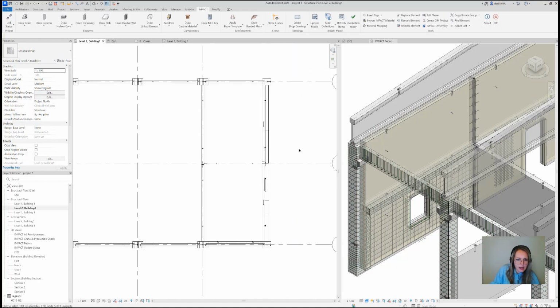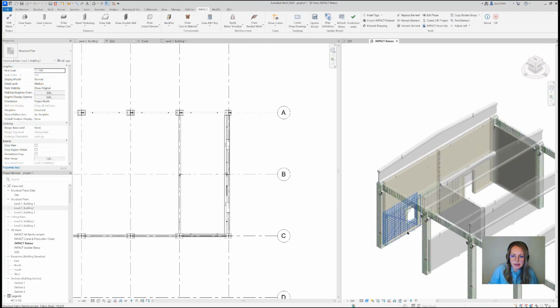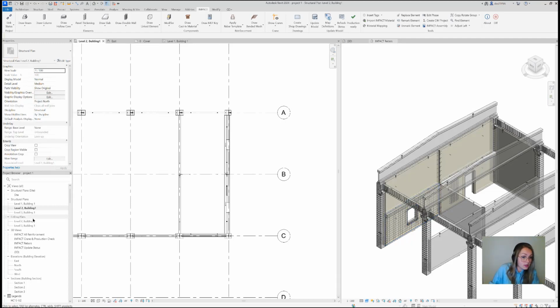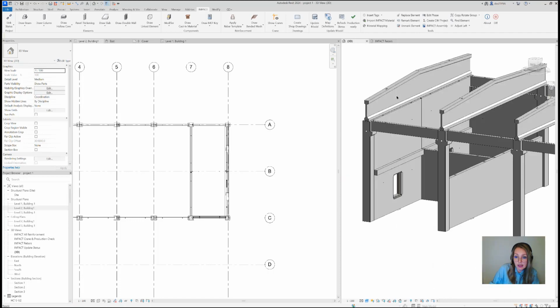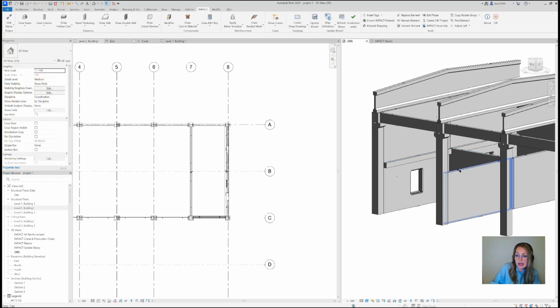We can go now and add the slabs, and the time is going fast, so let me just go on with the slabs. I guess some of you also want to see how to do it. In order to draw the slabs, I'll be on level 2, and I'm going to see the 3D here. As you can guess, we've done the panel thickenings because we want to lay down our slabs on the panel thickenings and on the massive wall here.